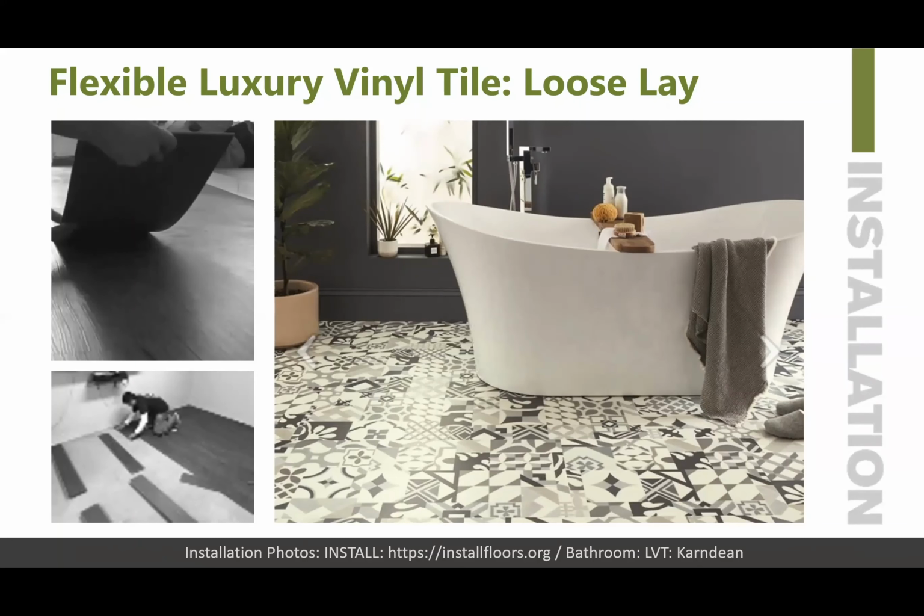Loose lay can butt up to thicker products as well. At 5 millimeters, loose lay tile can butt directly up to a number of thicker products that would normally require a transition, as indicated in our smooth transition section above. Substrate, substrate, substrate. Loose lay LVT is only as good as the substrate it is installed over and the installation practices used to install it.